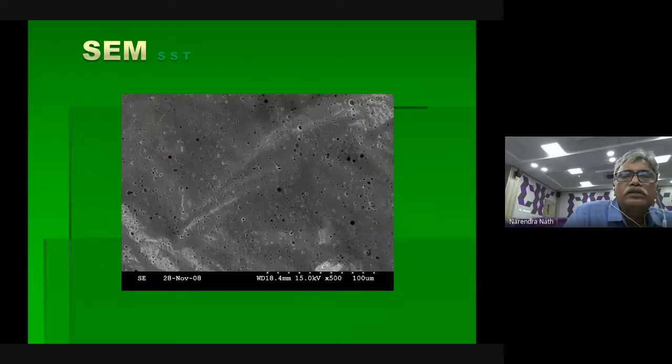And this is solid solution treated. So here also, if you look like this, you can see grains. But unfortunately, we are using HF. Any small amount of HF is very dangerous, and suddenly it will burn the surface. We tried for different times, up to 30-40 seconds. We miserably failed, but the optical one is coming out very nicely.